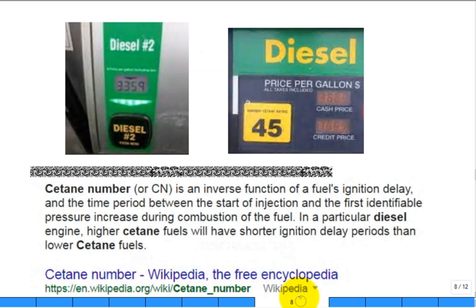All right. Let's talk a little bit about gasoline. We talked about it last time. What was the key index number that you pay a higher price for with higher grade gas? Yeah, it's octane. So in the United States, we use an anti-knock index, which is the sum of the research plus the motor octane number divided by 2.